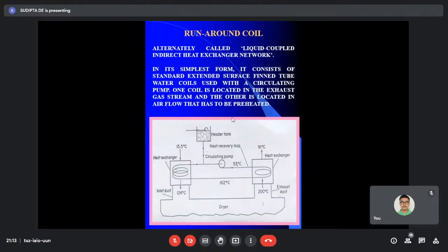So what you can do: the air being rejected to the atmosphere is cooler than the atmosphere, and you need cooling of the fresh air coming from the local atmosphere. So get heat exchange between these two. Your incoming air will then be cooled initially by the rejected air. What gain do you have? The heat load, that is, the subsequent cooling. That is not enough to cool it to the required temperature, but the subsequent cooling will be less, which will be done by the so-called vapor compression refrigeration process.